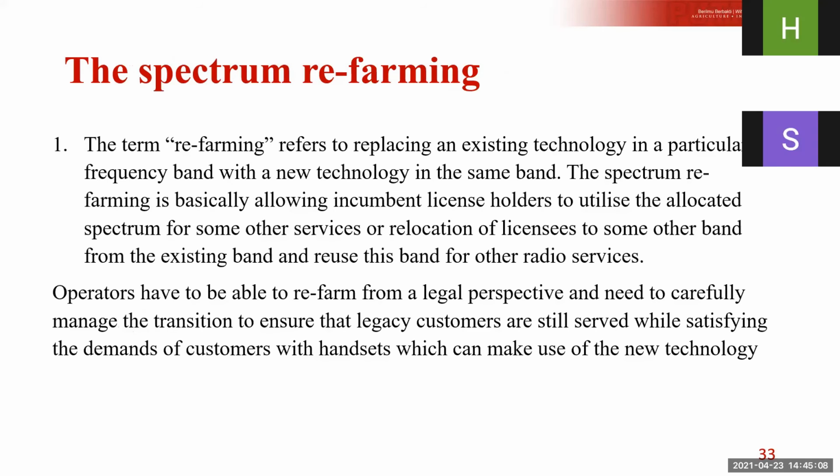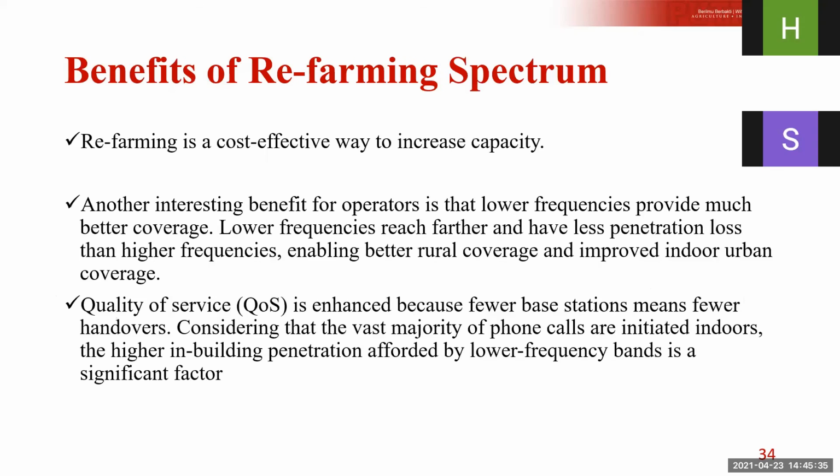What is spectrum refarming at the very beginning? The term refarming refers to replacing an existing technology in a particular frequency band with a new technology in the same band. Spectrum refarming is basically allowing the incumbent license holder to utilize the allocated spectrum for some other services, or relocation of the license to some other band from the existing band and reuse of this band for other radio services.